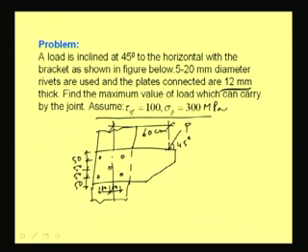So, we have 5 rivets of 20 mm diameter each and the pitch distance and edge distance has been given, which is 50 in vertical direction and 60 in horizontal direction. The eccentricity of load is 60 centimeter and the load is acting at a 45-degree angle with the horizontal base, and the tau_vf value, the allowable shear stress, is 100 MPa and sigma_p, the bearing stress, is 300 MPa, which has been given. Now, we have to find out the maximum value of load which can be carried.